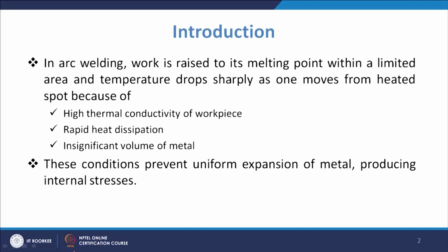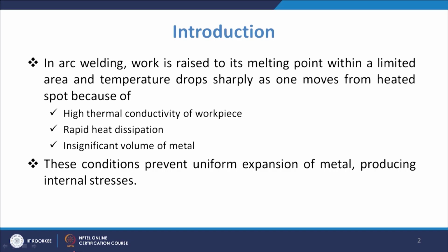First of all, in arc welding the work will be raised to its melting point within a limited area. So, in a very limited area you are increasing the temperature to a large value, and then the temperature will drop sharply as we move from the heated spot. The reason for the sharp decrease of the temperature is the high thermal conductivity of the workpiece.